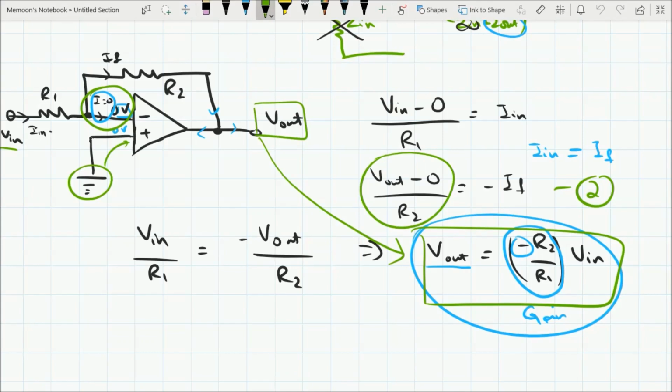A few things that we have to keep in mind while designing our operational amplifier circuits is that the gain we are giving to our inputs should and must not exceed the V out from the supply voltage. Otherwise, there would be a saturation and this relationship will not hold.